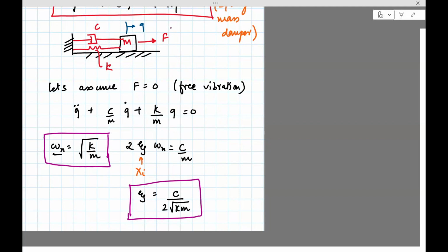The spring mass damper system will keep bobbing around the 0 position if there was no damping. And the damping constant tells you damping is like dissipation because there's a C involved. It sucks energy out of the system. So if you start this system from a non-zero Q or displacement, it eventually settles down to zero.